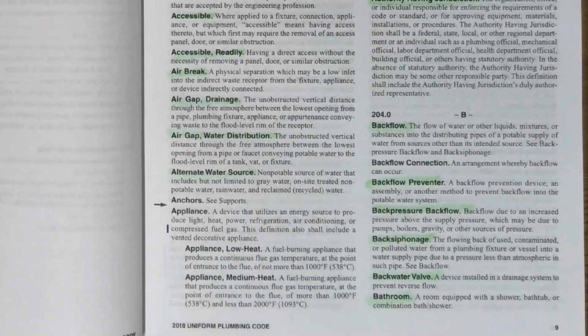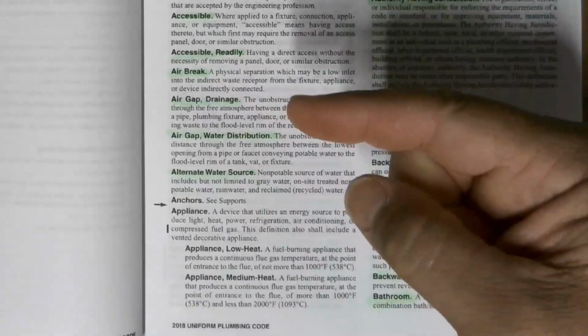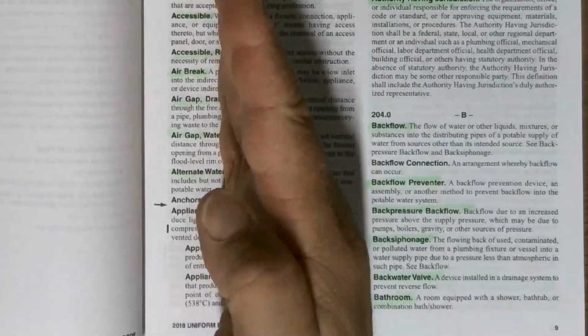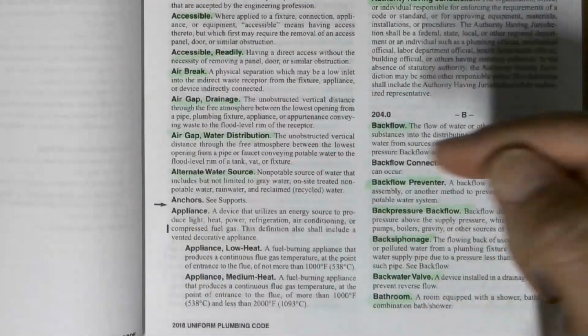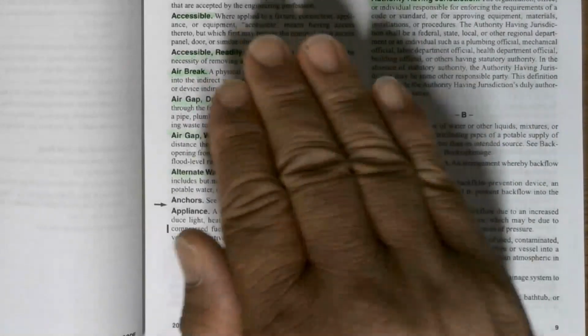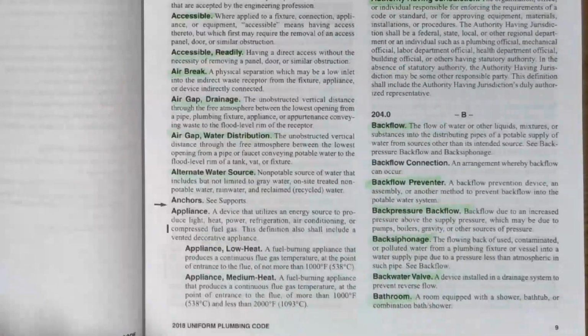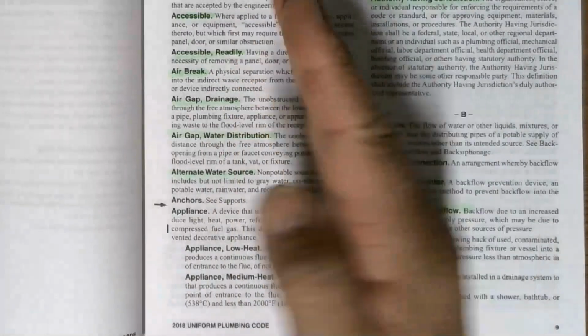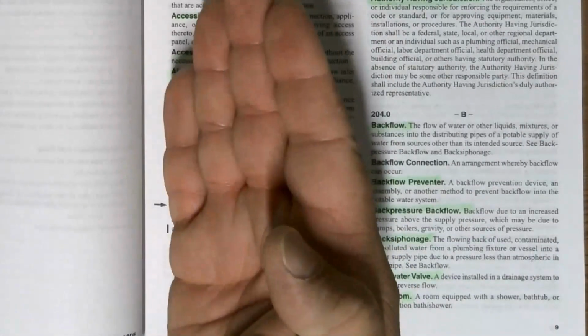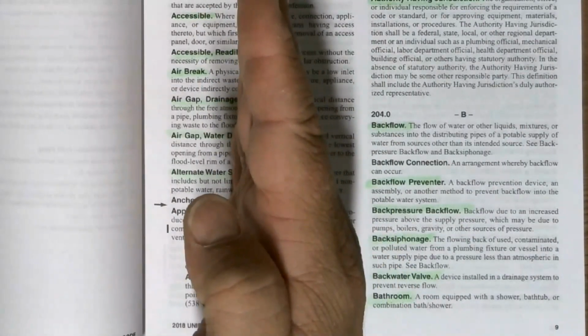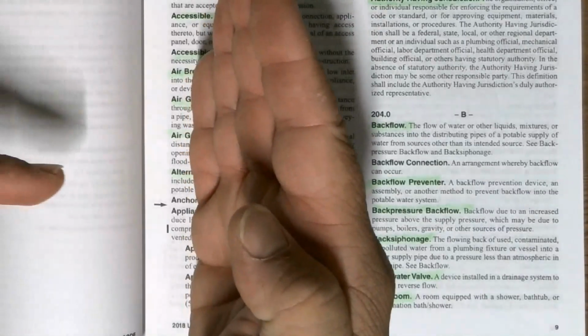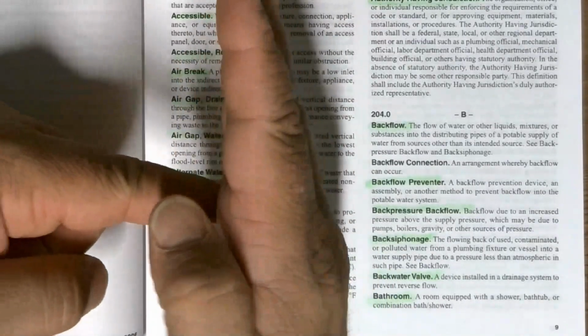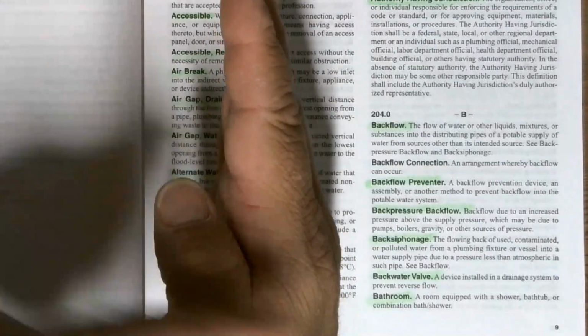With that being said, the one thing you're going to want to put in is a backwater valve. And all it is is a check valve. It prevents your flows coming this way. You put a backwater valve in right here. So as you flow out, it opens. The flap just kind of opens and everything goes out. However, so this is open, right? As the flow comes this way, it's going to hit this and it's going to close it. And therefore it's not going back into your house.